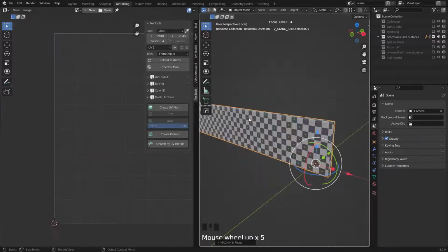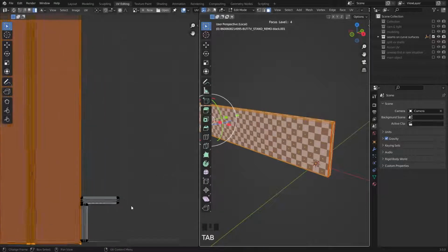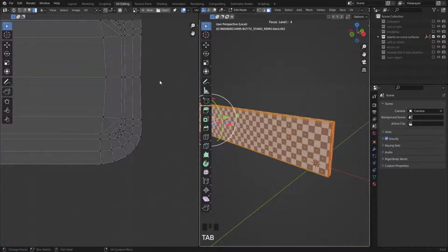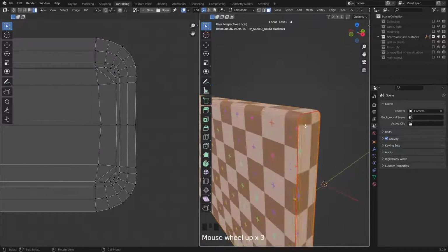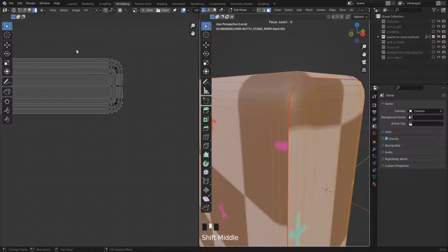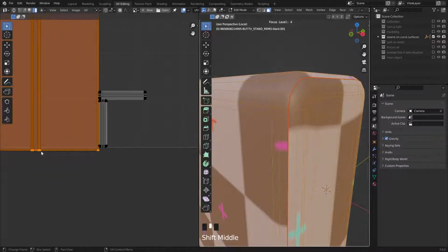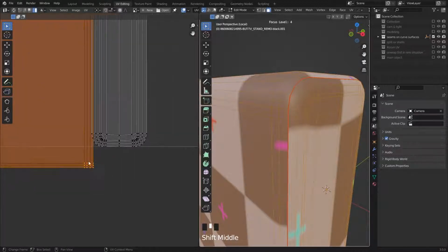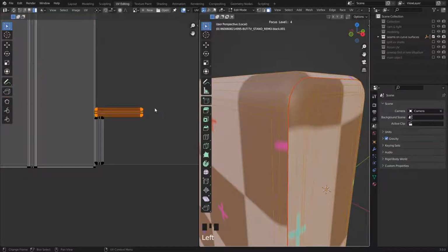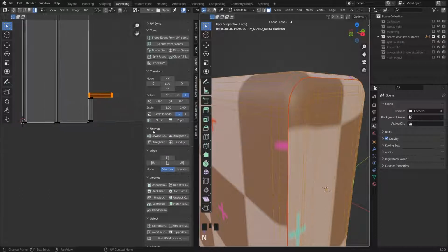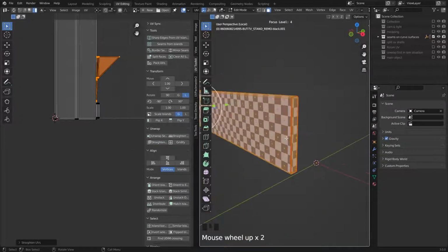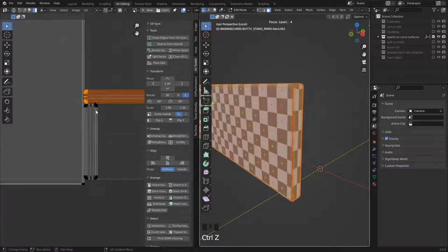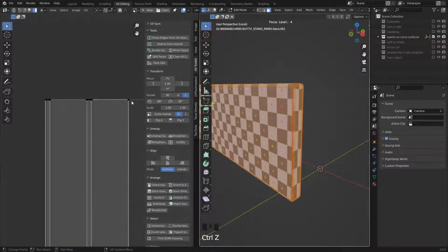So something very important: if I go here, you can see this area, it's here, so you cannot straighten this part because here we have this curved bevel, but in this UV shell you can see it's not a bevel, it's kind of rectangular, so you should never rectify this kind of UV shell. If you do it, you can see it distorts the UV shell. Okay, so straighten the UV shells, they are like this.